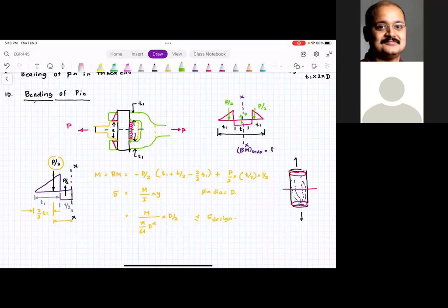You can't increase the gap because otherwise the joint would be wobbly. And actually that's dangerous. Why is it dangerous? Because you would have impact loading when the load is transferred, and that is significant. But what I can do is add a sleeve. I can add a deformable sleeve somewhere here.